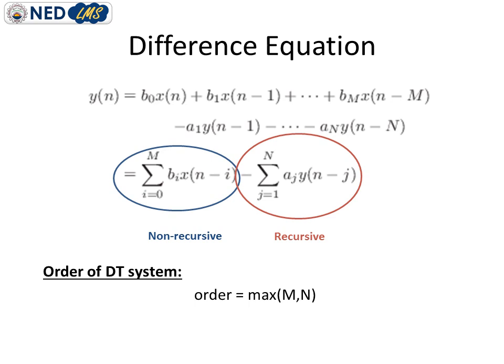So if we need any system to behave very sharply, or which can select the frequency very sharply, we need to increase the number of zeros and poles, and this can be increased by increasing the number of delays, or we can say as we increase the value of m or n, which is the delay, the poles and zeros of the system increase.